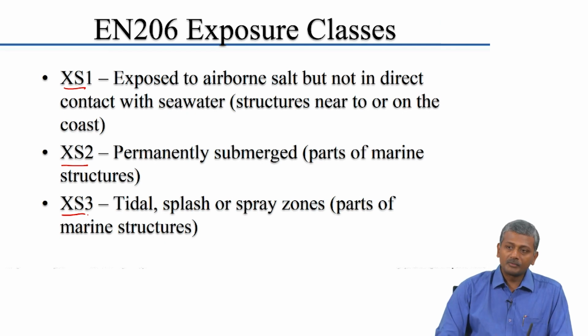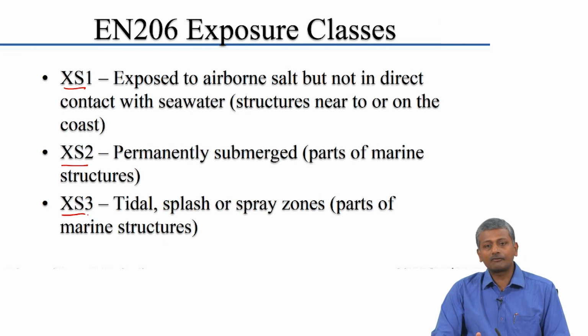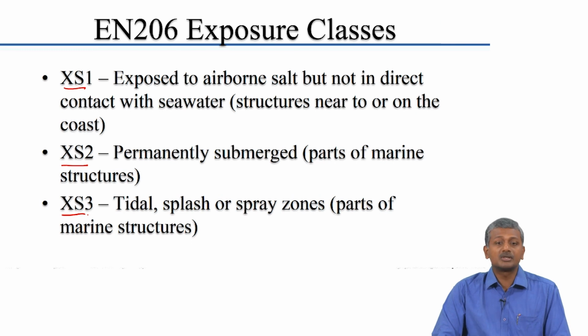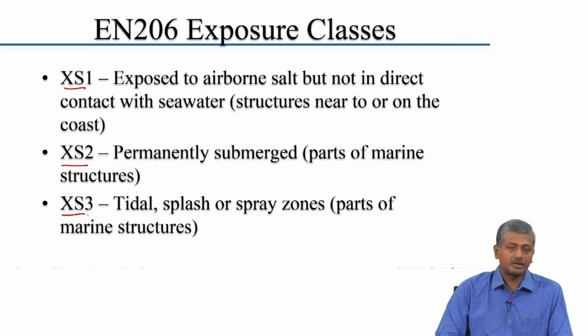Okay. Apart from this, they also have a classification for chloride attack from other sources. For example, when you have chlorides in groundwater, like the situation is in Delhi. Okay. In Delhi, which is so far away from the coast, a lot of chloride exists in their groundwater, and that chloride has created a lot of corrosion related problems.